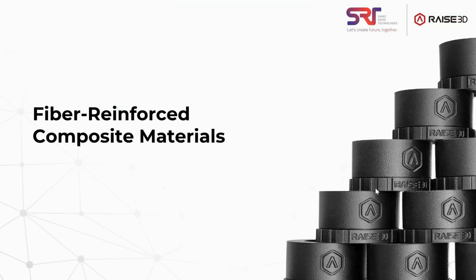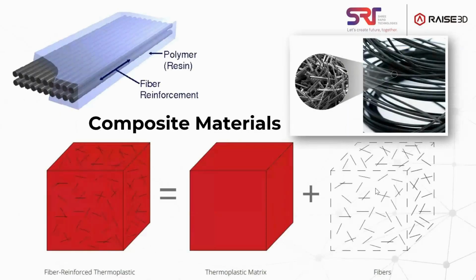So, what are fiber reinforced composite materials? Basically, these composite materials are created by adding chopped or continuous fiber to a thermoplastic matrix. The most popular reinforced fibers are CF, carbon fiber, glass fiber, and Kevlar. They have superior strength to weight ratio, and basically the embedded fibers provide strength and stiffness along the direction they are laid on, while the thermoplastic matrix maintains the cohesion of these fibers and allows them to take the loads.